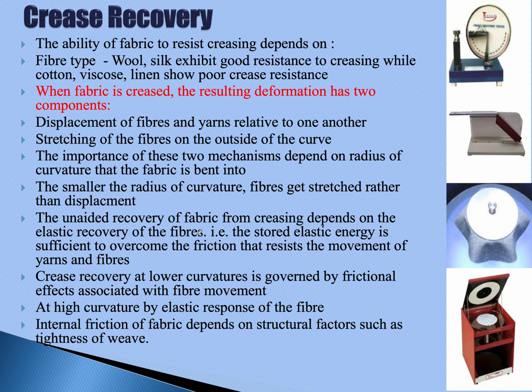And the unaided recovery of fabric. Unaided means when no mechanical force is applied or when the fabric is not subjected to washing. At that time, how does it recover from this creasing? It will depend on the elastic recovery of the fibers. That is, what is the stored elastic energy and whether that stored elastic energy is sufficient to overcome the friction that resists the movement of yarns and fibers. So it is the interplay between these two forces which causes the fabric to recover from the creased position.